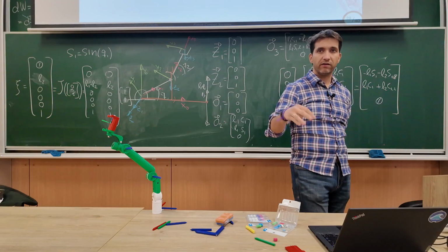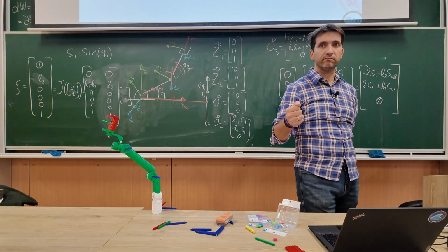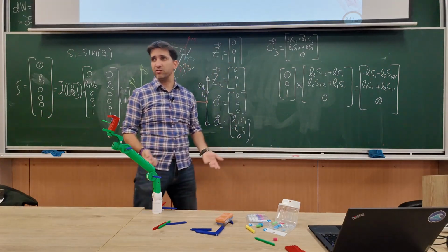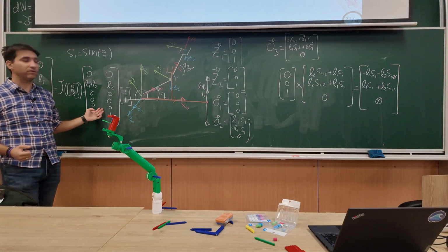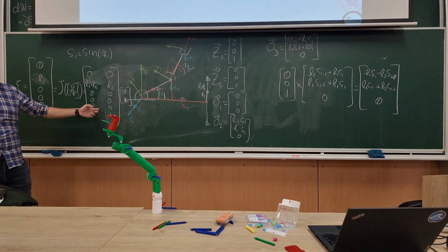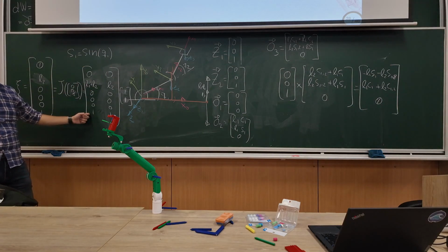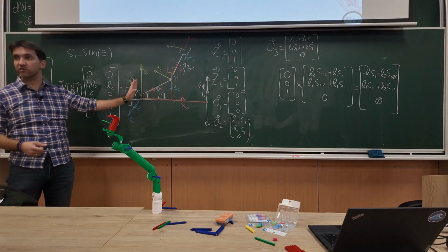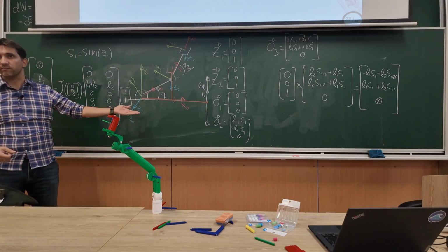What is the condition so that I can invert the matrix? To have determinants different. Yes. And even more so, to calculate the determinant, it has to be square, right? Is this one square? No. Right, so I cannot do it always. What's the condition for this one to be square? This Jacobian always has 6 columns, so it needs to have 6 rows. It always has 6 rows, so it needs to have 6 columns as well. When does it have 6 columns? When I have 6 joints.